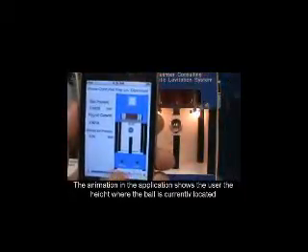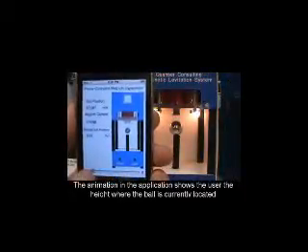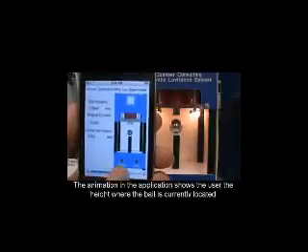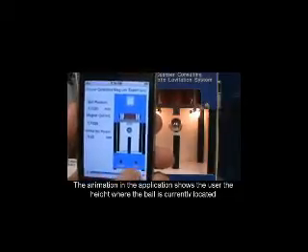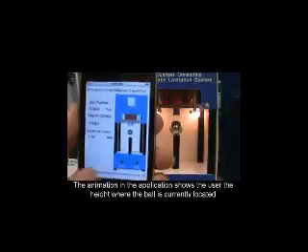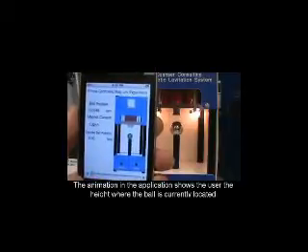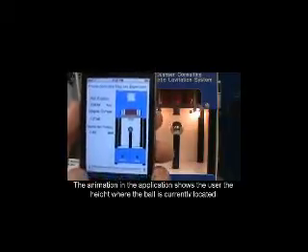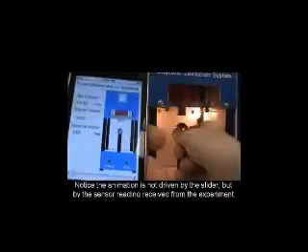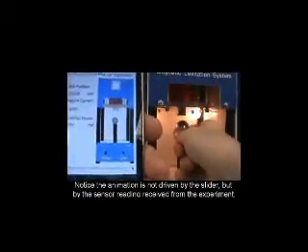In order to control this system, we implement a proportional plus integral, or PI, controller for the electrical subsystem to regulate this current, as well as a proportional plus integral plus derivative, or PID, controller for the mechanical subsystem to regulate the ball's height.